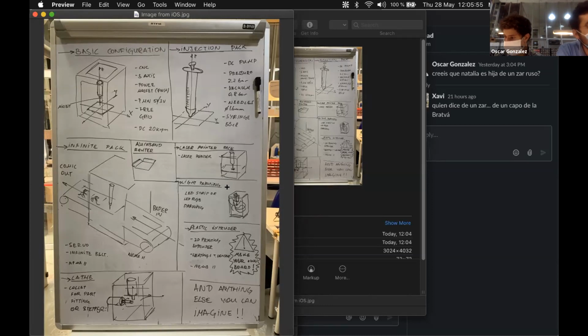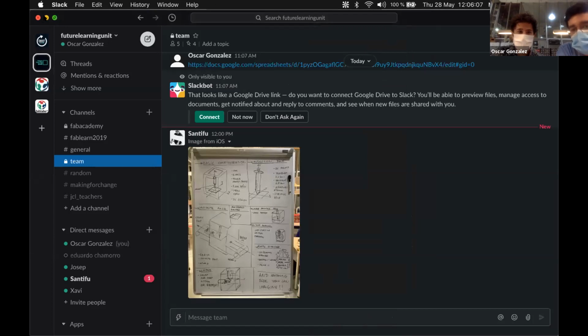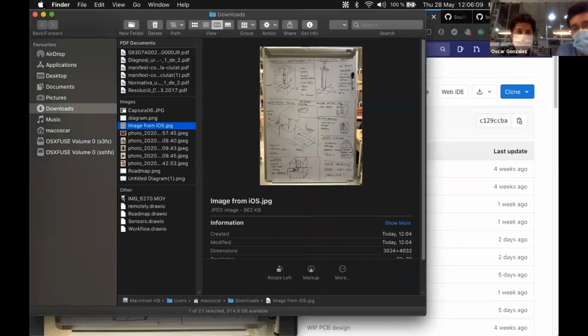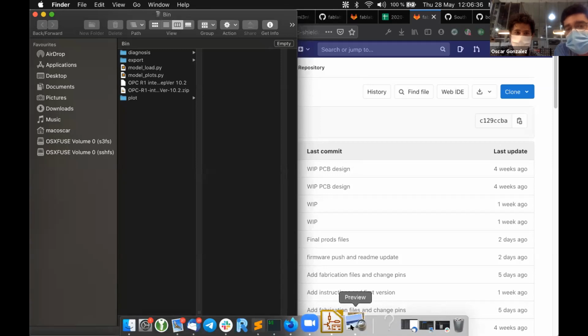A networked control system behaves completely different and has a lot of benefits. For example, each stepper has a small PCB, a small board that has its own controller, its own stepper driver, and basically you have an address that you are calling. Let's say it's a network of motors. That's good because you can expand the system really easily. For example, you can just connect another motor with its own stepper board and call it with the same address that another axis that you already have.